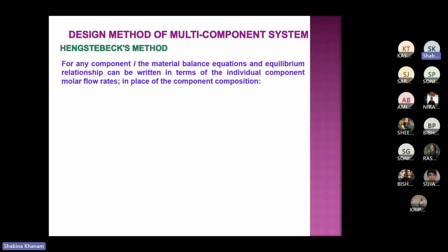The main concern over here is that whatever separation is required, based on that we define the light key and heavy key, and above light key is light non-key and below heavy key are heavy non-keys.